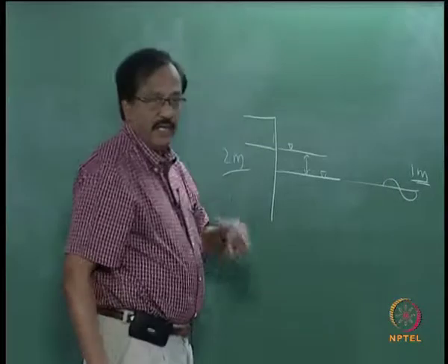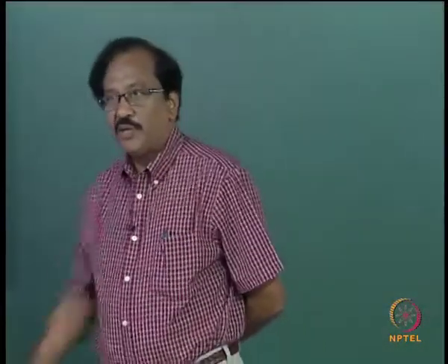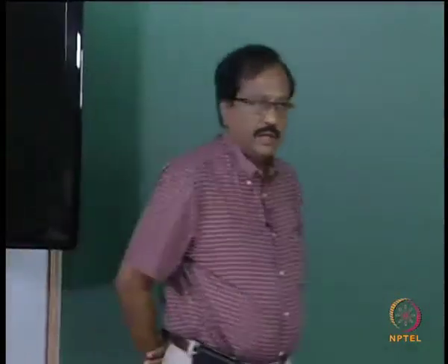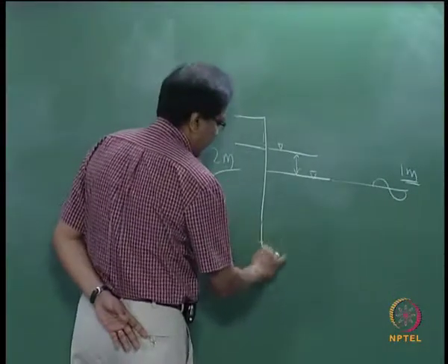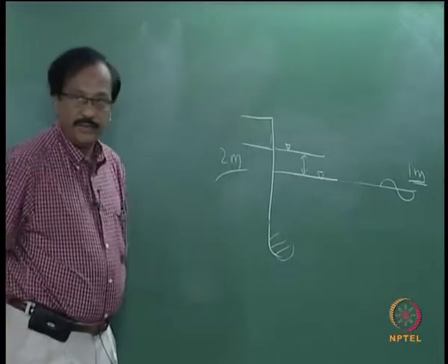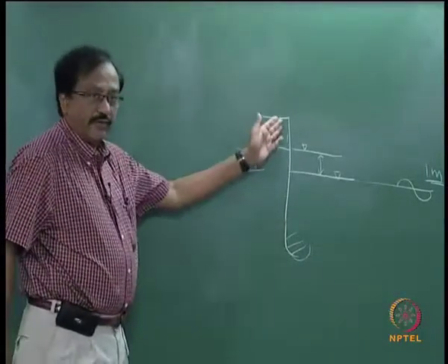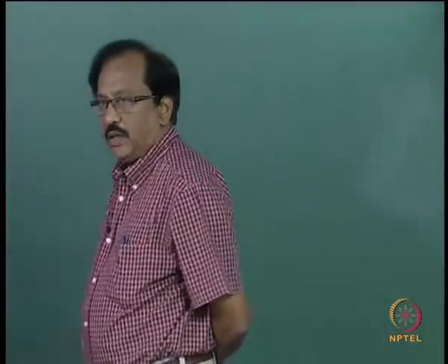So, when you have the wave height on the wall to be more, naturally the orbital velocities etc. will be more, and so the force exerted by the presence of the structure is going to increase. You are going to have scour problem, you are going to have the forces being increased that would act on the vertical wall.